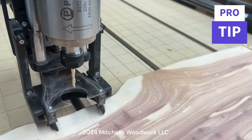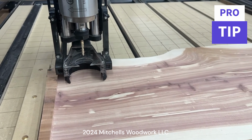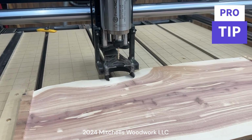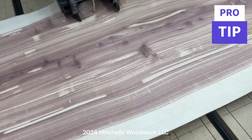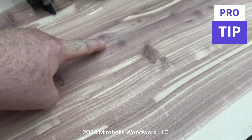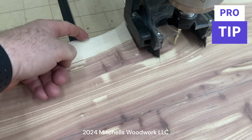It's kind of close there. I really couldn't tell about that. All right, let me get over here, push stop, and we'll do it again. So I ran the dry run a couple more times and discovered that I needed to move my XY from here down just about an inch, because I was getting way too close up here.